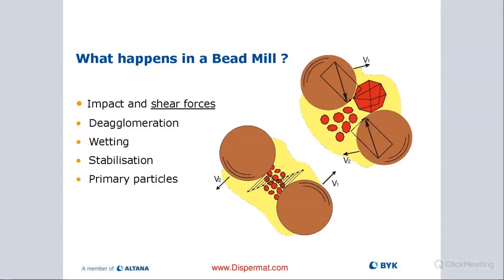Right before the point of impact, you can see on the top picture where basically that force is causing these particles to shear off. And that is actually what's happening inside of a media mill. So contrary to what a lot of people think, that when I'm milling, I'm actually crushing my media or my pigment particles or other particles in between two balls, that is actually a very unlikely thing to happen. Probability is very small. Why is that?